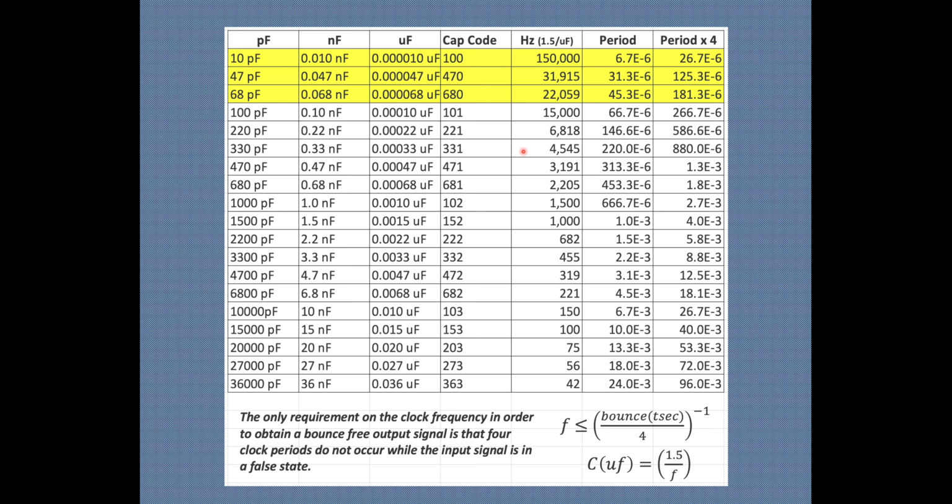But here's a spreadsheet we did, a cheat sheet so to speak, that shows what we used. A 1.1 nanofarad capacitor gave us the 2 milliseconds, and you can go down to 5 milliseconds like the tactile switches. That'll handle most all tactile switches. You use a 2.2, and it'll probably work with the newer ones with the 1 nanofarad. But yeah, 1 nanofarad or 2 nanofarads will work.